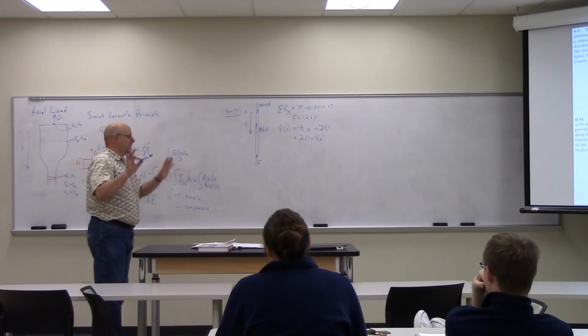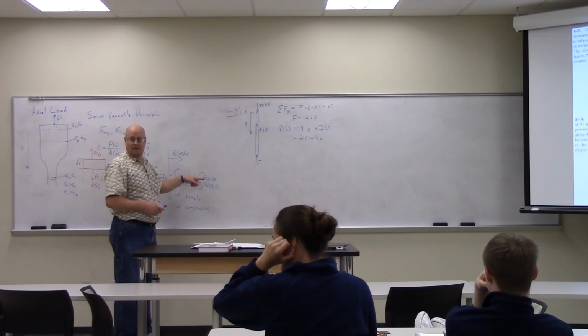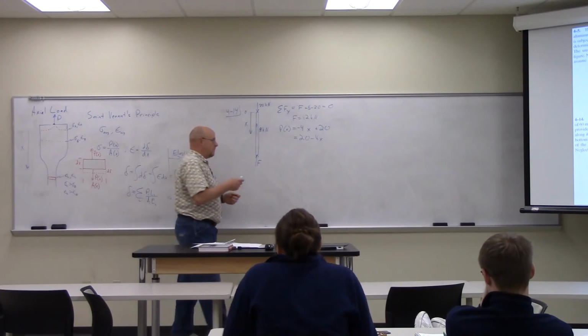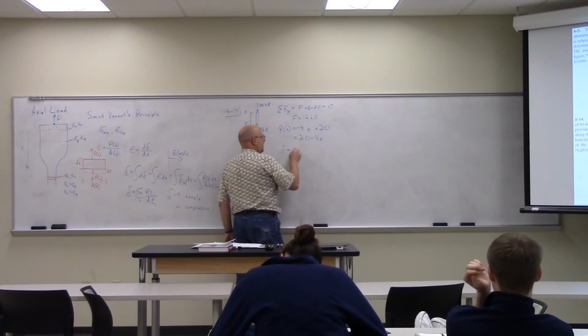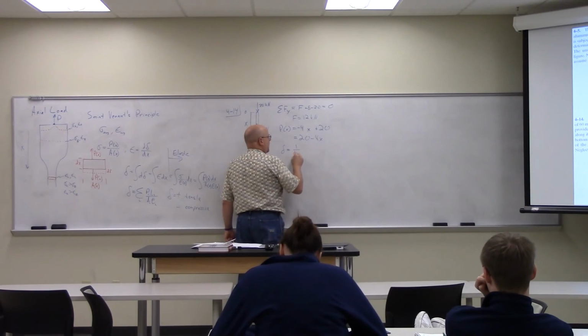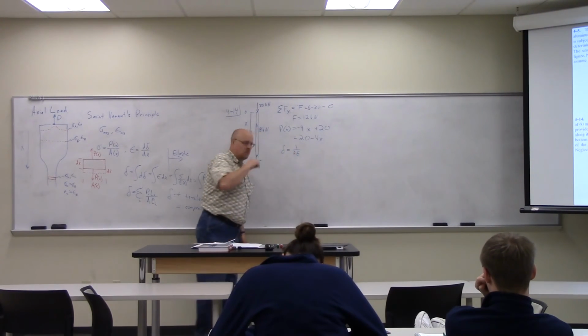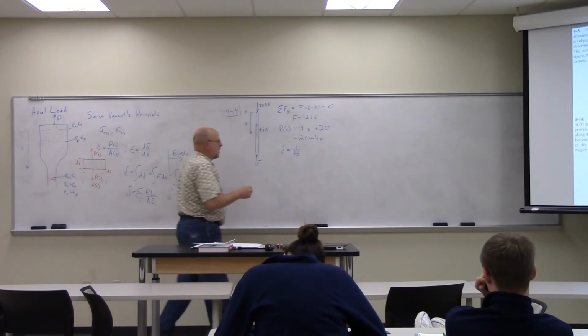Let's not digress. Okay, so now we have an expression. We have to come back to our delta, but because P is a function of X, we have to write delta as an integral. First we extract 1 over AE, because A and E are not functions of X, so we pull them out of the integral.